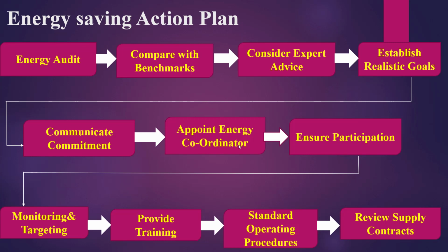By monitoring at regular intervals, unexpected changes in consumption, perhaps due to the faulty operation of equipment, leaks, poorly set controls, or other sources of waste, can be detected rapidly and corrective actions taken. Regular monitoring also provides a flow of detailed and comprehensive operating information, which is a vital component of good management.